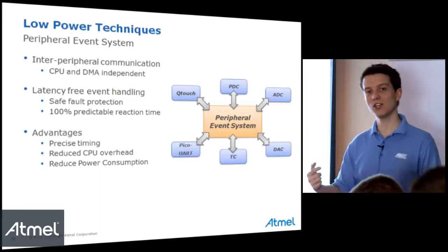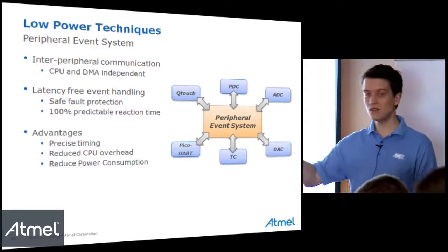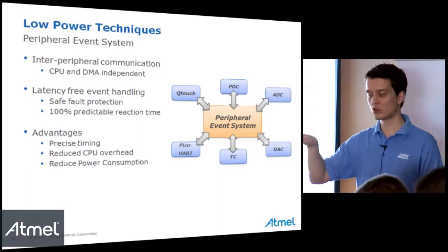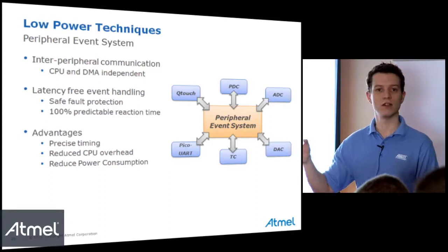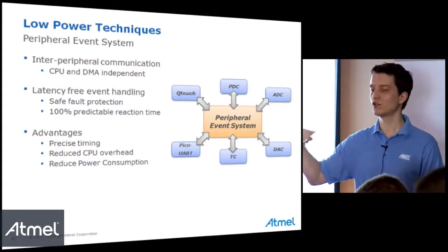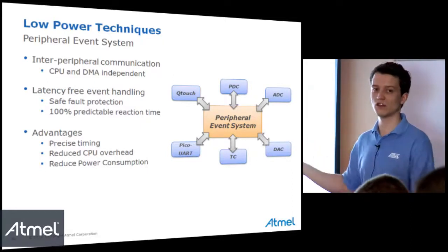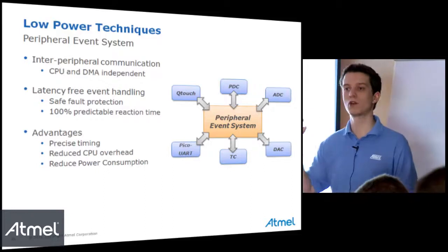Then at each end of conversion, it will send an event to the PDC. The PDC will take the result of the ADC and store it in memory, and also manage the number of acquisitions that you will have to do, for example, 256. So after 256 acquisitions, it will send an interrupt to the microcontroller, or to the core. Then the core will be woken up.